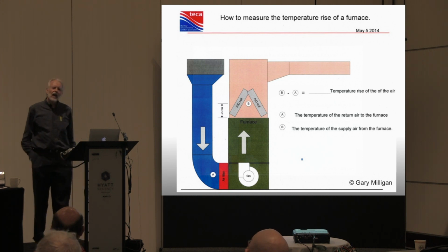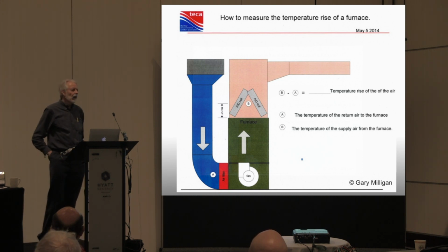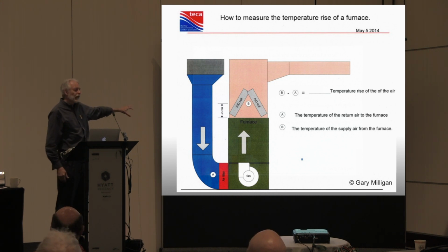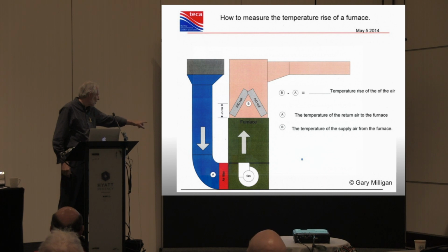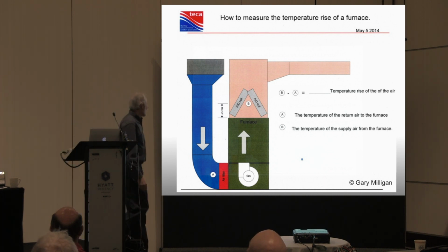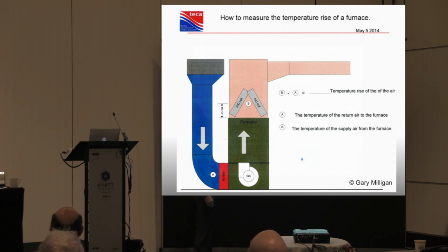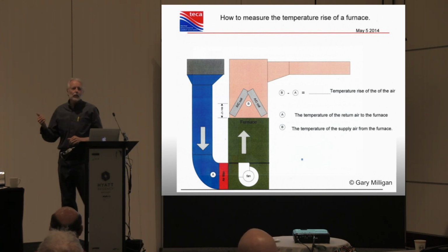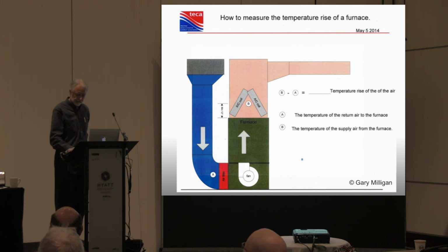Well, furnaces today have what we call a proper heat rise. An installed furnace will have a cold air return that comes back at 72 degrees Fahrenheit. It goes down that corner band through the filter, goes through this fan, it goes up through the appliance, and the temperature difference between B and A is what we call the temperature rise of that appliance. Every appliance has a sweet spot. And I'm going to talk about that because it's a direct impact to you as builders. Every appliance has a sweet spot. You operate out of the sweet spot, you pay.